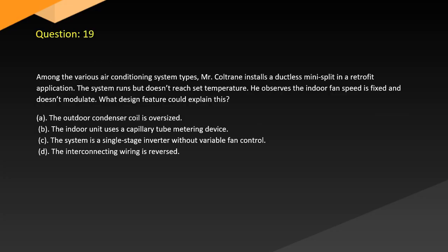Question 19. Among the various air conditioning system types, Mr. Coltrane installs a ductless mini-split in a retrofit application. The system runs but doesn't reach set temperature. He observes the indoor fan speed is fixed and doesn't modulate. What design feature could explain this?